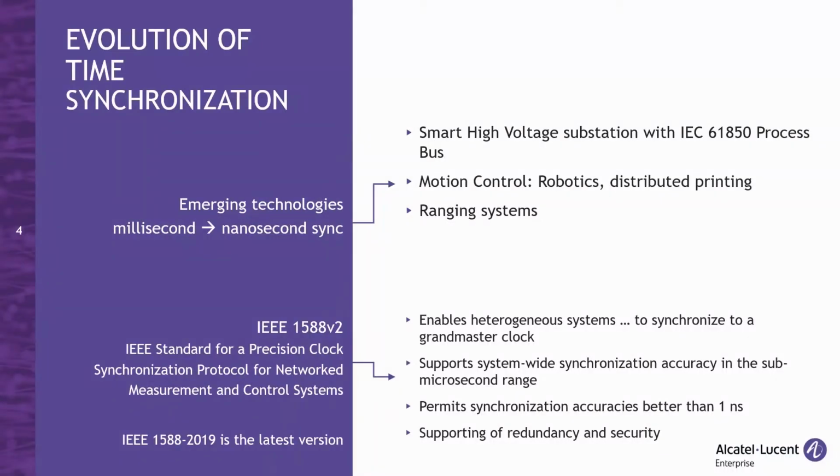Evolution in time synchronization is triggered by evolution in different technologies. Working with telecommunication networks, all of us at one point worked with NTP or Network Time Protocol, one of the first packet timing protocols. If I tell you that the first RFC related to NTP has the number 958, it would be easy to understand how far we go back in time. It was published in 1985, and the accuracy of clocks delivered by NTP was about 100 milliseconds. Of course, it evolved further with time up to version 4 and was capable of accuracy in milliseconds or sub-milliseconds, which was sufficient for telecom networks at that time.